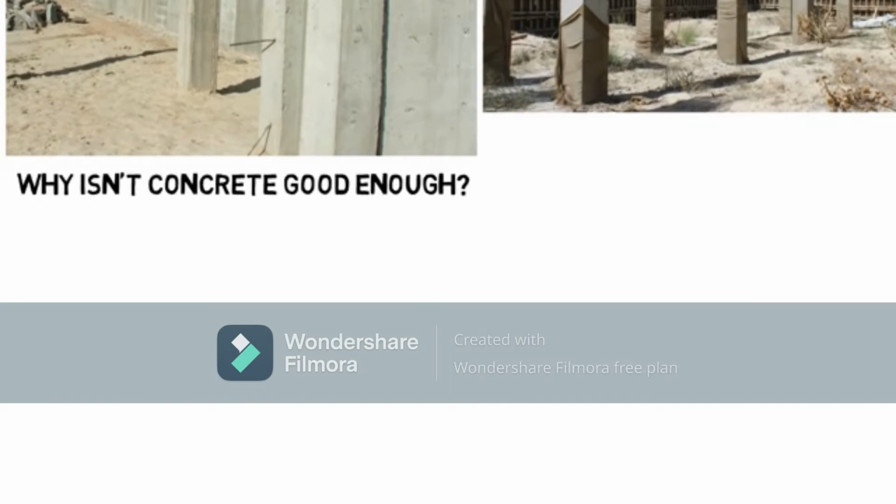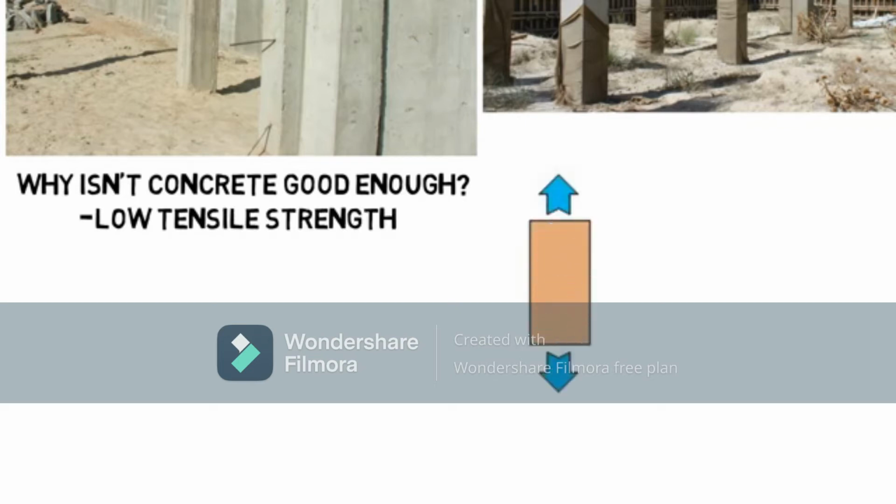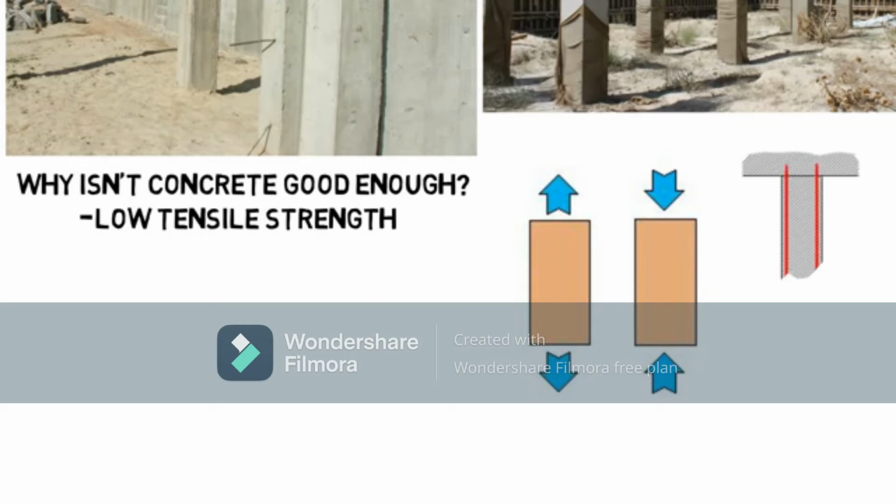Well, concrete alone, once hardened, has low tensile strength, as in it does not handle being pulled very well. However, it's okay with being compressed. But to counteract that low tensile strength, they add steel beams and pour wet concrete, which hardens around them, and then those steel beams have high tensile strength to counteract those types of forces on the structure.